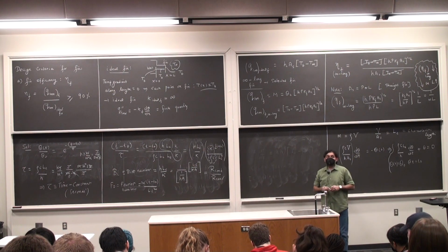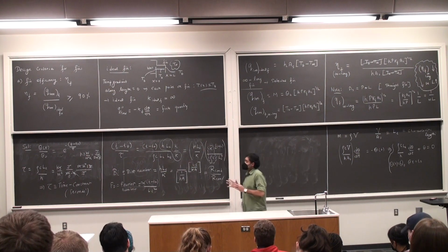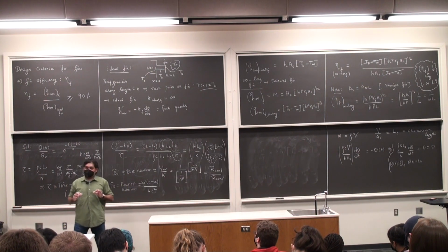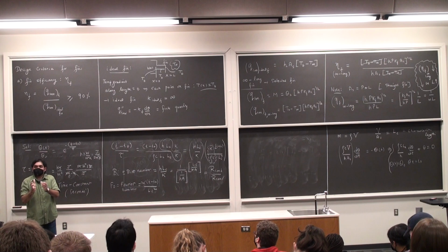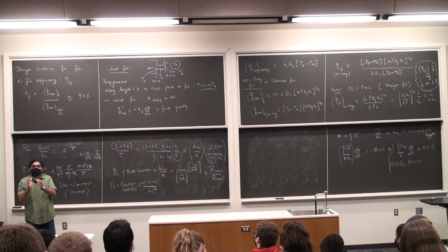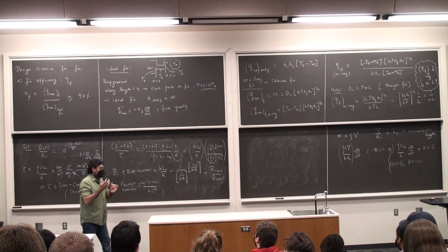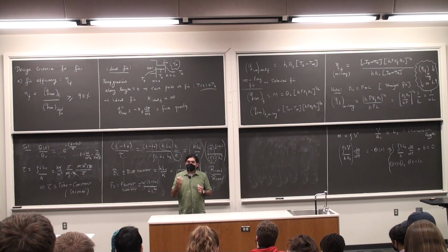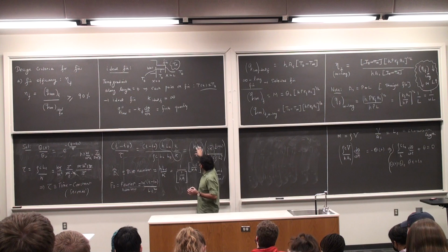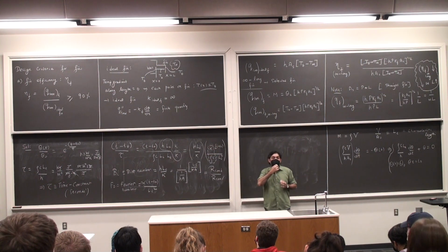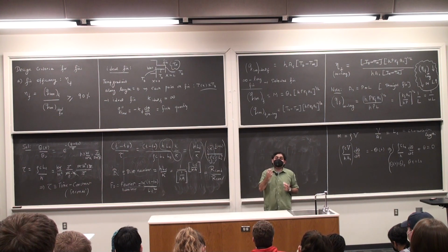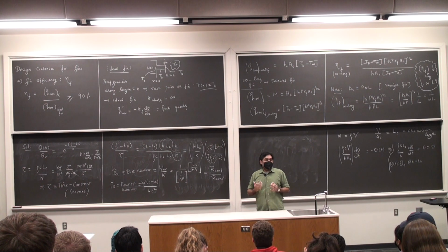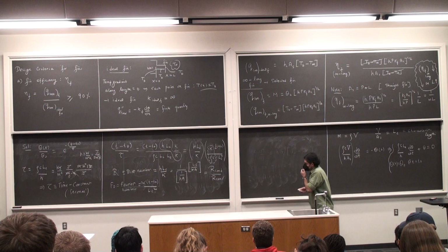Okay, so the Fourier number is representative of the rate of heat propagation through the body. If the Fourier number is very high, then this approximately means that your system thermal time constant is very small, because you see that 1 by tau is proportional to the Fourier number. If the Fourier number is large, the thermal time constant is small, the response of the system is very swift. And vice versa.